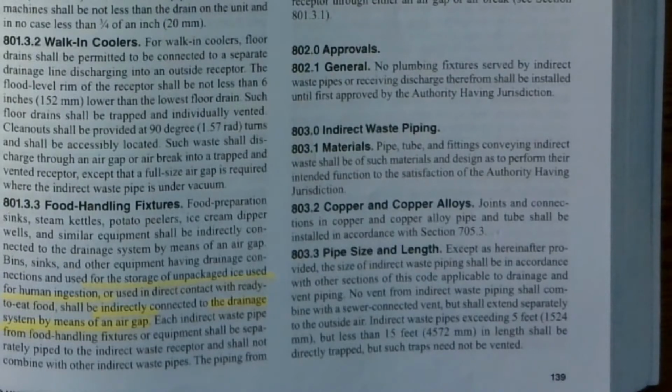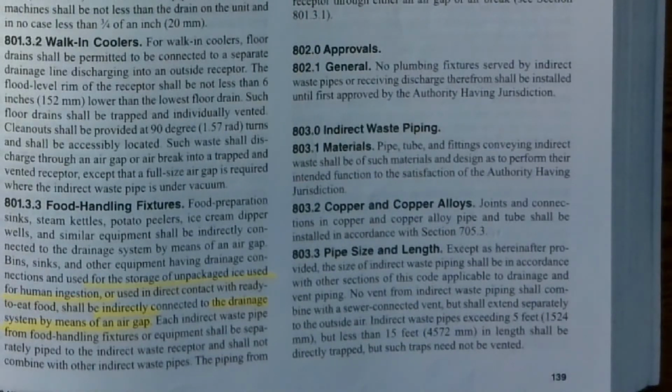And also, really quick, if you are venting any type of a system that is indirect waste, that indirect waste vent has to go separate, because the whole point is to not have any type of contamination with the two separate systems. Okay, you're not going to hook up an indirect waste vent into a direct vent system, because then if that sewer backs up and you have a positive pressure, or maybe there's a vent clog in the regular venting system, that's going to backfeed into the vent system of the indirect, you're contaminating the foods through that indirect drain.